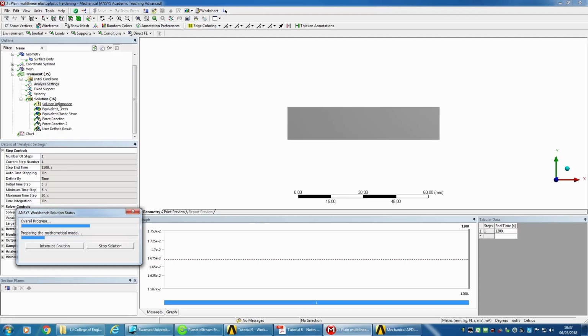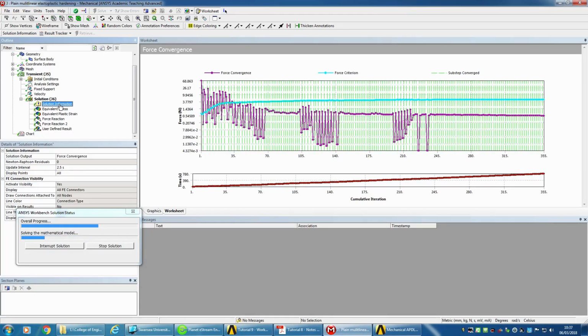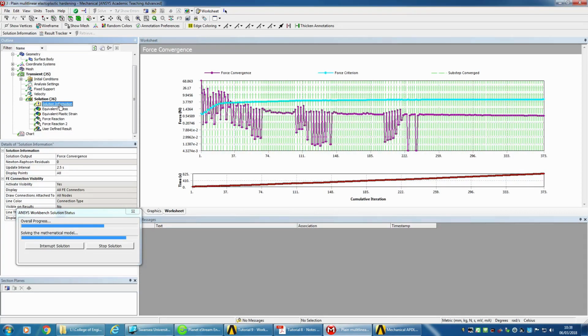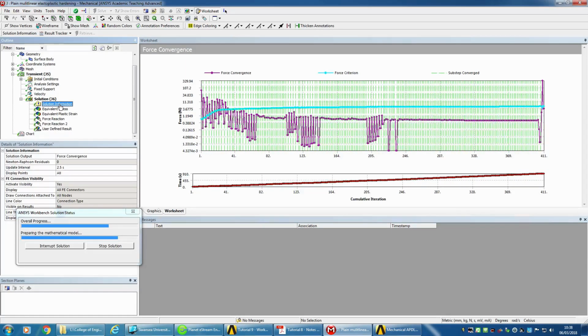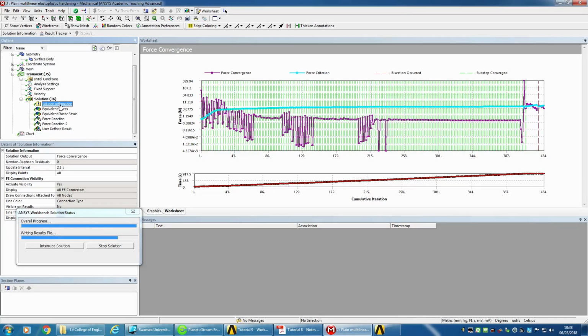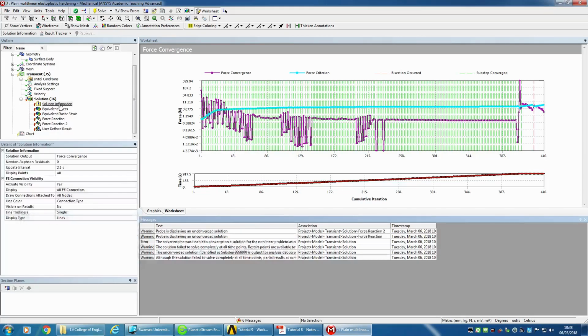Okay, let's see how that's going on. These particular values of the analysis settings have been craftily picked out for you to run in real time here. They wouldn't necessarily be the best ones for your solution. So if you've got more time to run this, and you don't just need to run it in 1 minute flat in front of 50 people, then I would suggest that you decrease your time step and increase your mesh size. Generally a good recipe for getting better solutions.